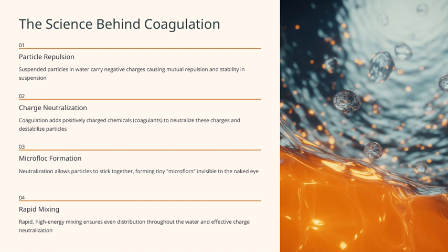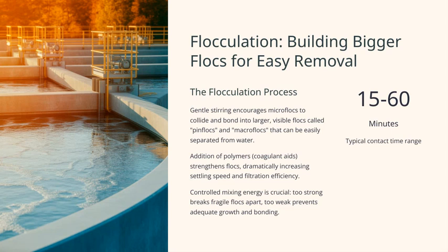Finally, rapid mixing is essential. By quickly and thoroughly mixing the water, we ensure the coagulants are evenly distributed. This high-energy mixing promotes effective charge neutralization and helps the microflocs form more efficiently throughout the water. All of these steps work together to remove impurities and clarify the water, which is at the heart of the coagulation process.